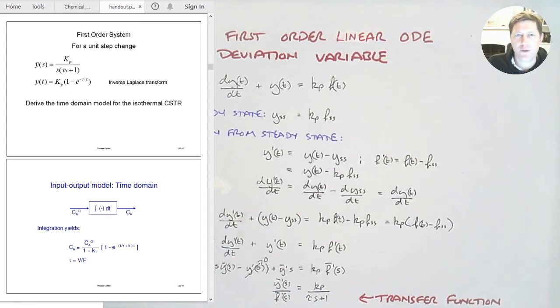So now with that we can find what the response of the system is by multiplying the transfer function by the input, and the input function for a unit step change is simply 1 over s. So now we have this s term that's appeared on the bottom, and that's what's accounting for the input for the unit step change input.